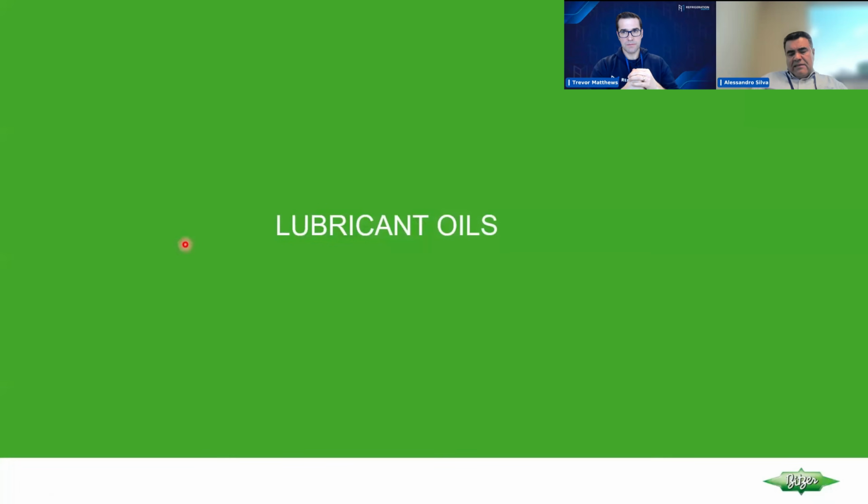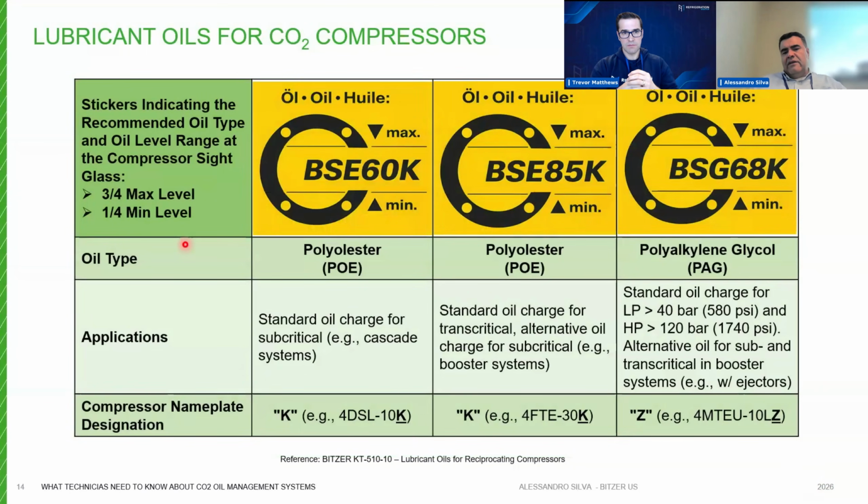So let's review the lubricant oils. I put together here the Bitzer original oils. Our recommendation is to use our original oils as much as possible and never mix different oils together.